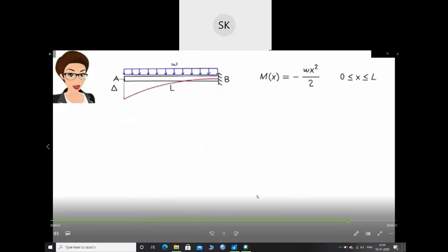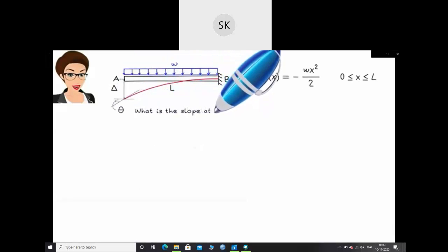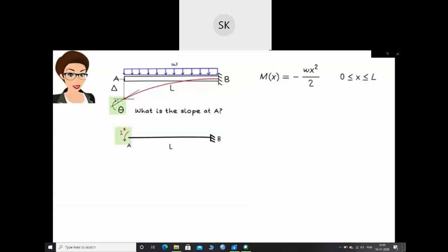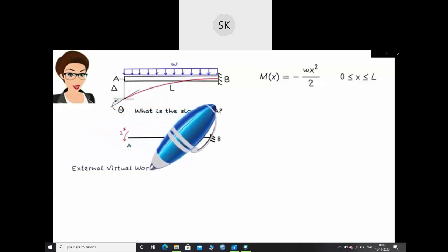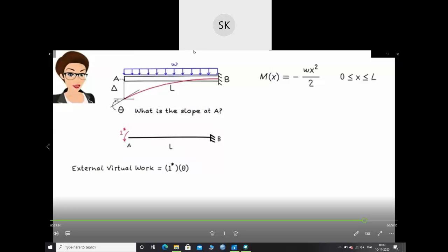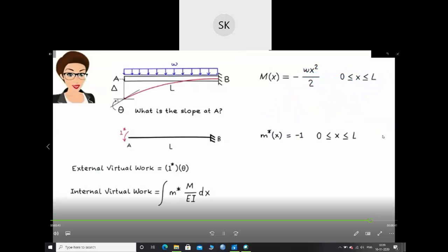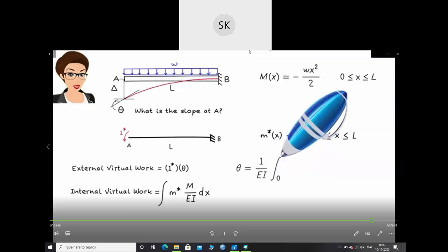Suppose we are also asked to determine the slope of the elastic curve at A. This can be done easily using the method of virtual work. Since we are looking for slope, denoted by theta, we are going to place a virtual unit moment at A. This way, the product of the rotation and virtual moment is virtual work. So the expression for external virtual work becomes 1 times theta. The expression for internal virtual work remains the same. However, now m star is the moment equation due to a unit virtual concentrated moment applied at A. So the cantilever's rotation at A is...